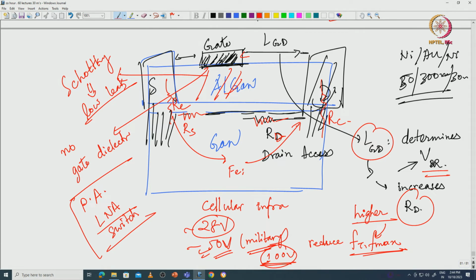We do record power densities in AlGaN/GaN HEMTs, and people have biased even at 150 volt, but that is very difficult to get as a supply rail in a radar, a satellite communication system or a cell phone. So typically 28 volt is the most common, and then next is 50 volt, you should keep that in mind. Because you do not go to higher voltages like 600 volt or 900 volt, you do not need a gate dielectric. The gate leakage is already low at the voltage levels that we use.